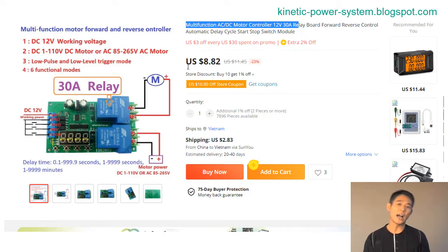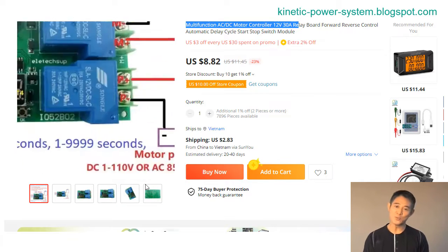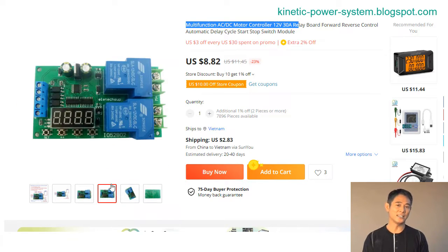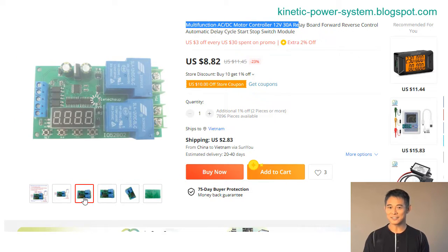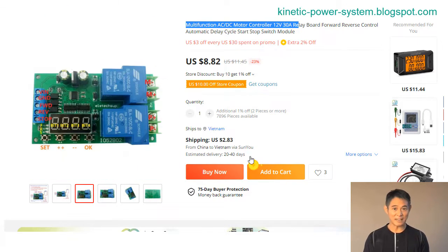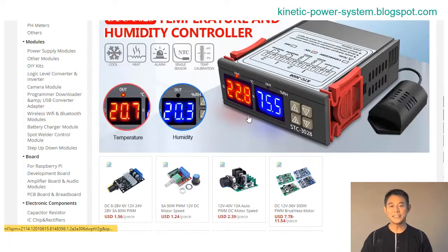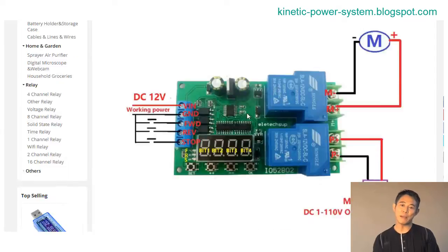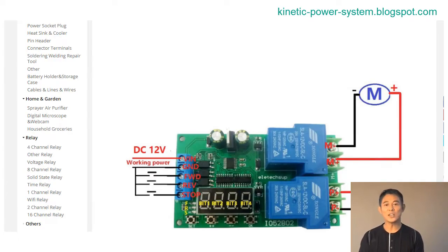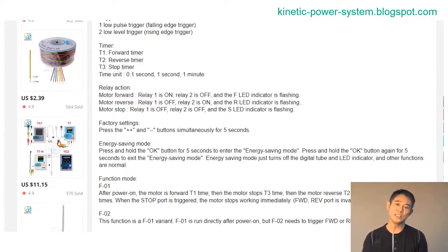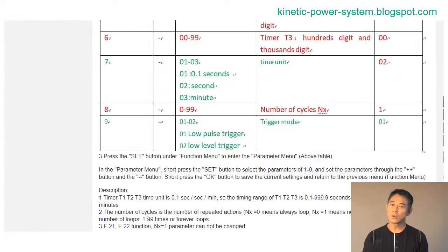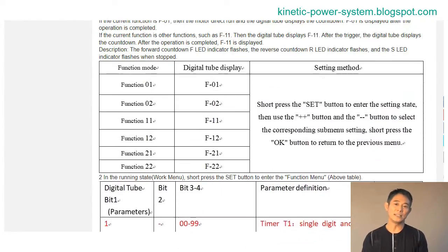How do I choose a DC motor controller? The first consideration is the motor's nominal voltage. DC motor controllers tend to offer a voltage range. For example, if your motor operates at 3V nominal, you should not select a motor controller that can only control a motor between 6V and 9V. This will help you cross off some motor controllers from the list.